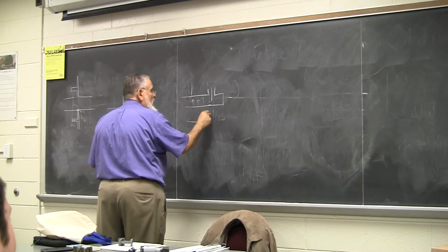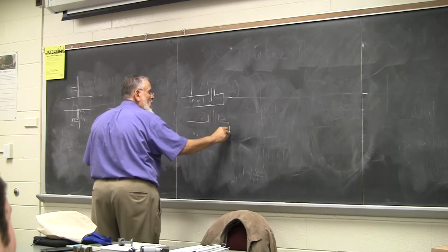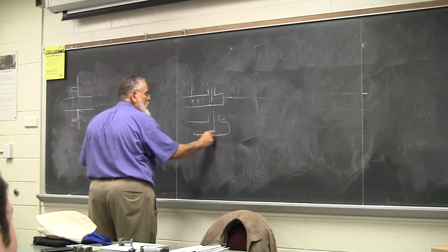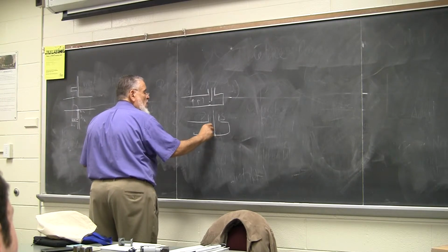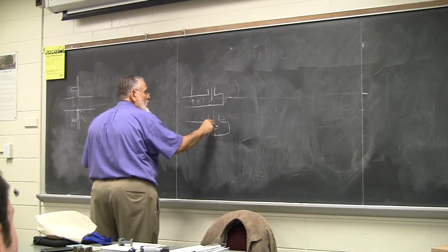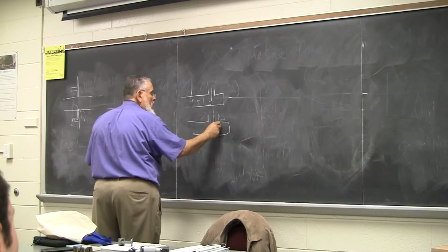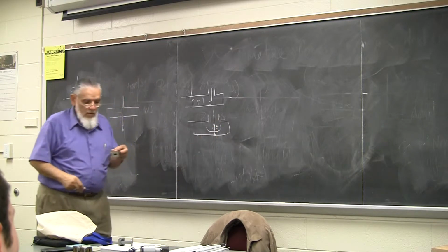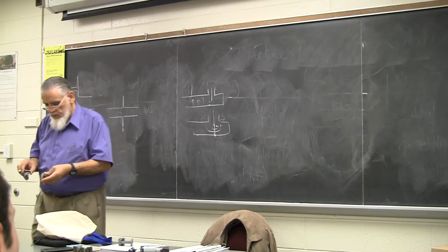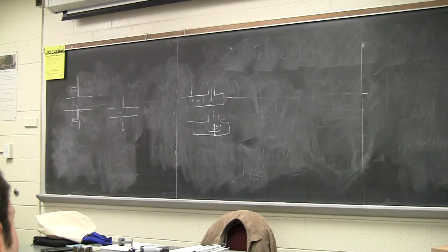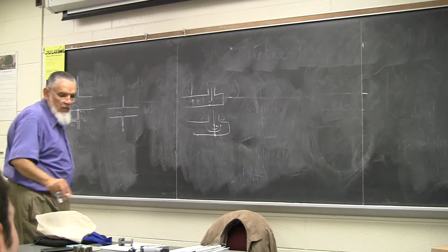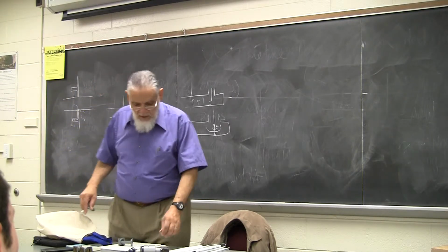And there is a magnetic field one, which is actually a short here, and relies on the current here to cause a magnetic field that will launch your TE10 mode, right? So the magnetic coupling and the electric coupling, both coming from an N-type connector.